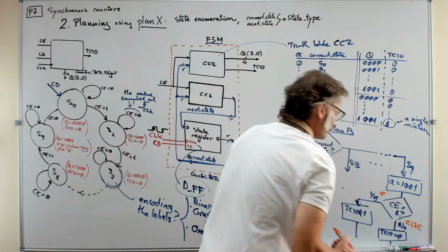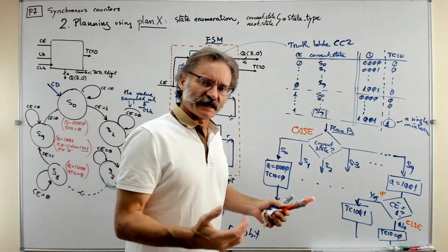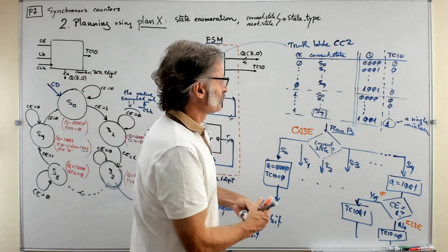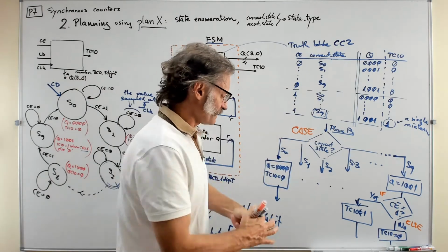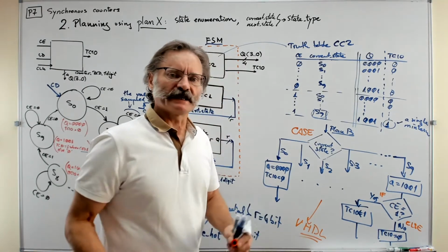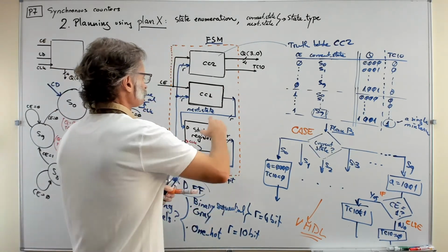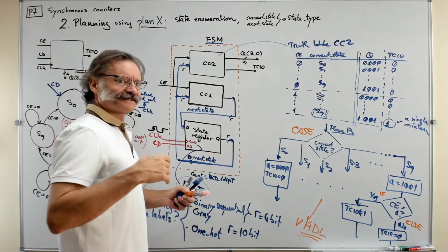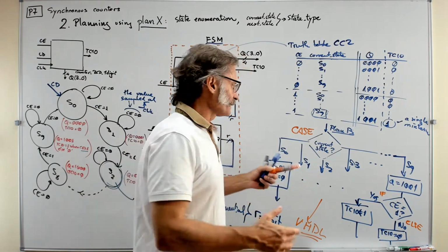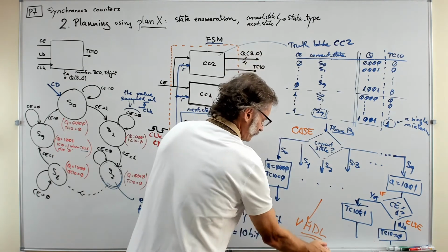So as you can imagine now, browsing the given VHDL file that is there for you to copy, adapt and study, you have to see that the final implementation of the VHDL from this flowchart is not that difficult in the end. You will find the entity and then the definitions of the state type, state, next state, and current state, the state enumeration S0, S1, S2, and then the truth table CC2 translated to a flowchart, and finally to this VHDL sequence.